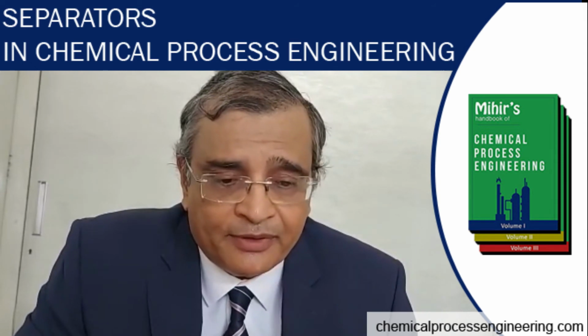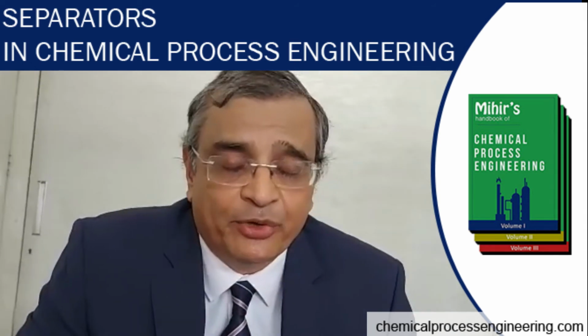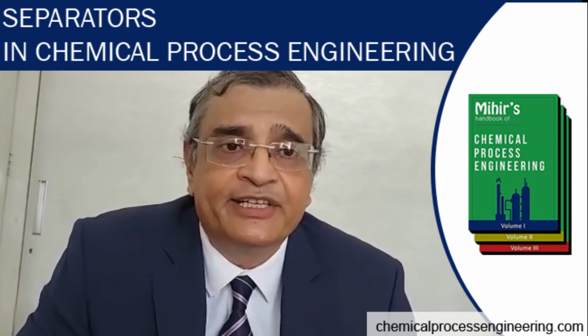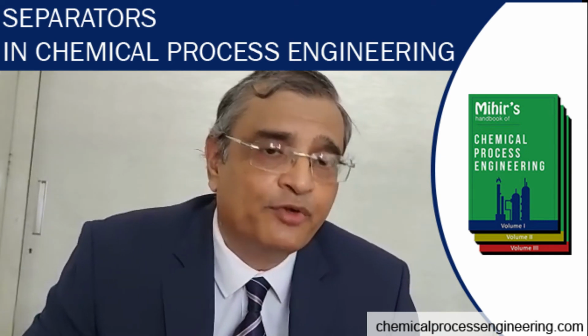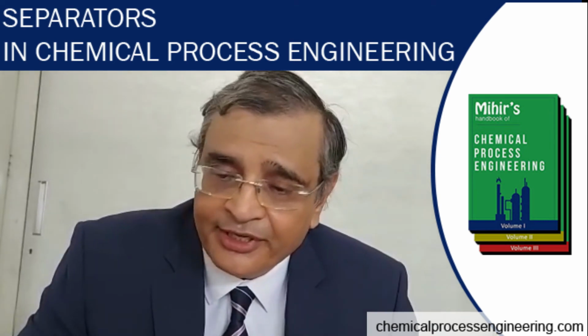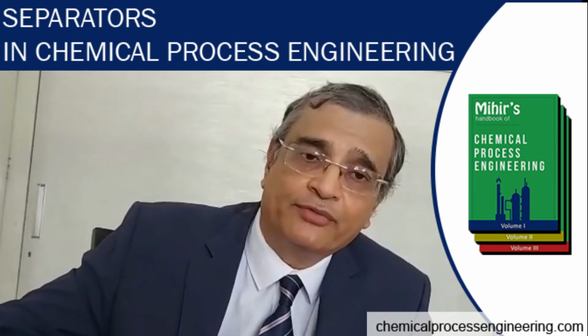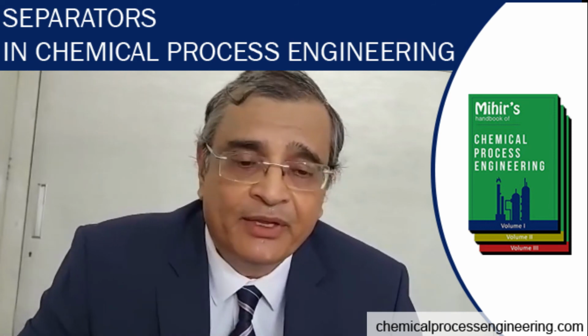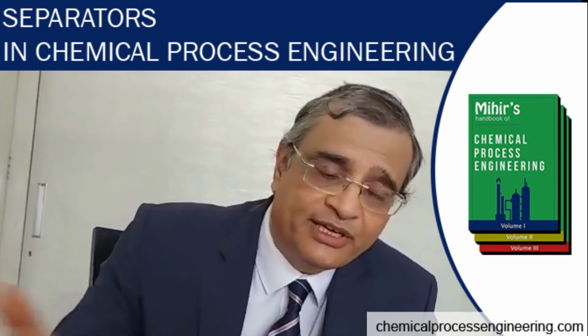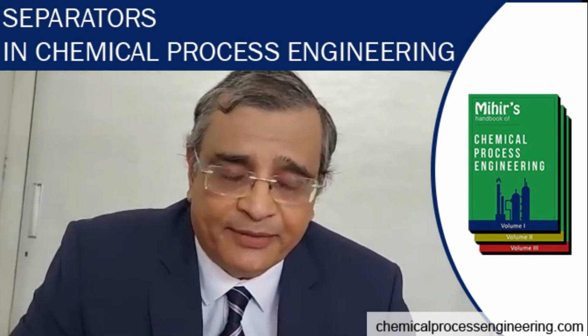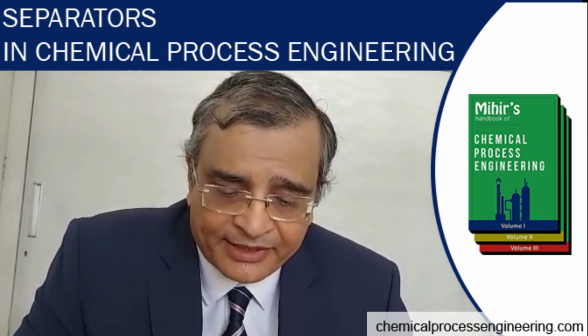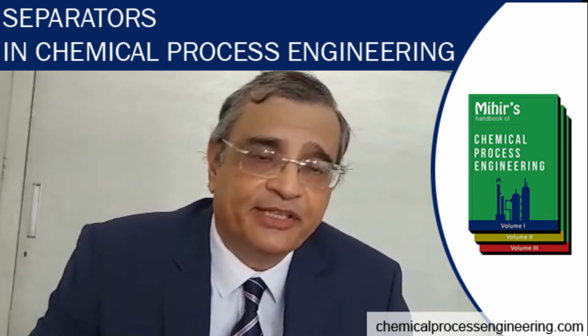Now we will also discuss the flare KOD. The flare KOD is designed by another method which is called the drag coefficient method. It is a safety issue. You cannot give a mesh at the outlet of the gas leaving the flare KOD, because in case that gets choked, the whole safety of the relief system is compromised. So the flare KODs are designed with the drag coefficient method.